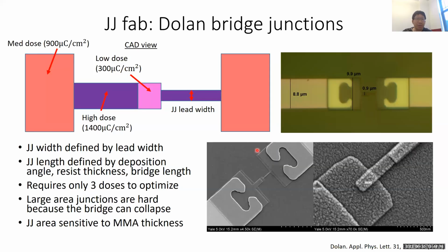So Suhas, maybe I missed this, but there's a related question. Would you have native oxide on the capacitor layer before making the junction? So what do you do to ensure they have metallic contact in the shape you just mentioned? Yes, I'll go over the deposition process in a little bit more detail in the next few slides. But yes, in order to remove that oxide, you have to employ some sort of surface treatment, in particular an argon ion beam clean.